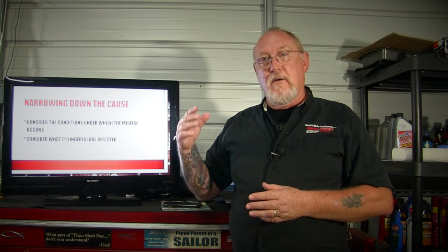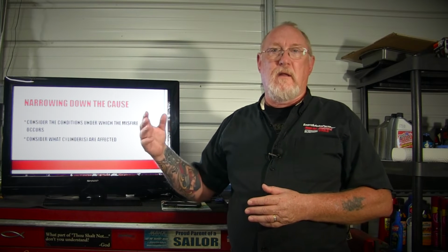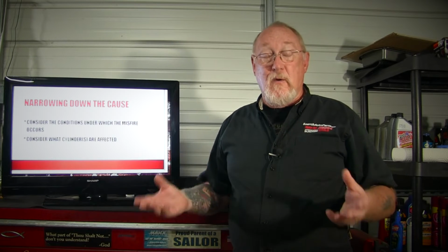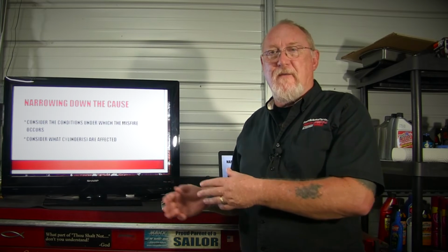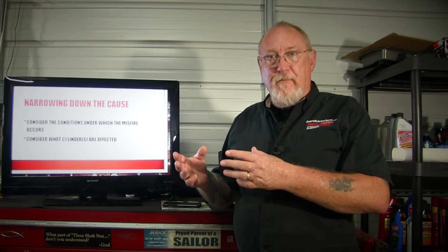An engine at idle takes very little fuel, doesn't it? But if it's pulling up a grade with a full load behind it, 3/4 throttle and a lot of load, then it's going to require a lot of fuel. Well, what if the fuel system isn't able to deliver the volume of fuel that's needed? Could that result in a misfire? Sure. But will that lack of volume affect it at idle? No, it won't. So looking at the conditions is already going to put a few things at the top of your list of possibilities that you need to inspect and go after.